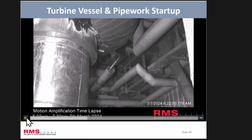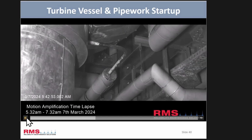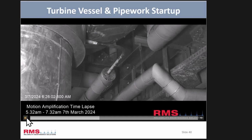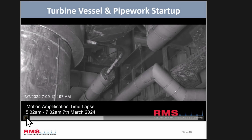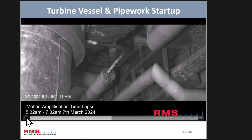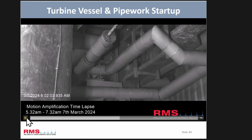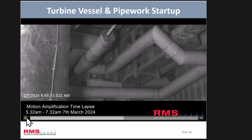The customer was having pipe fractures, and wanted to know if it was due to thermal growth over a period of time. So this is over a 2-hour period, and you can see what's happening there, and you can set your data plots off there as well to show you how much movement actually occurred in that vessel over time. So that's another function of the camera.